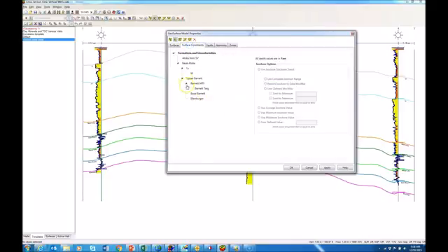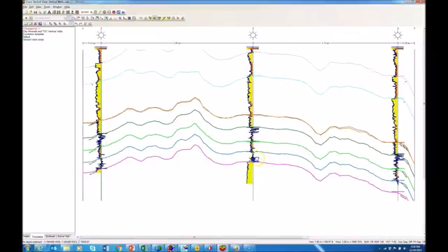Now in addition, I'm going to take the Atoka from SeisVision and make it be the controlling conformance surface so that the basal Atoka and all subsequent surfaces will conform to the seismic surface. However, these other surfaces will honor their well picks. I'm going to apply that. And notice now we have a much more detailed interwell conformance from the Atoka from SeisVision down through the basal Atoka, through the basal Barnett, Barnett maximum flooding surface, basal Barnett, and Ellenberger.